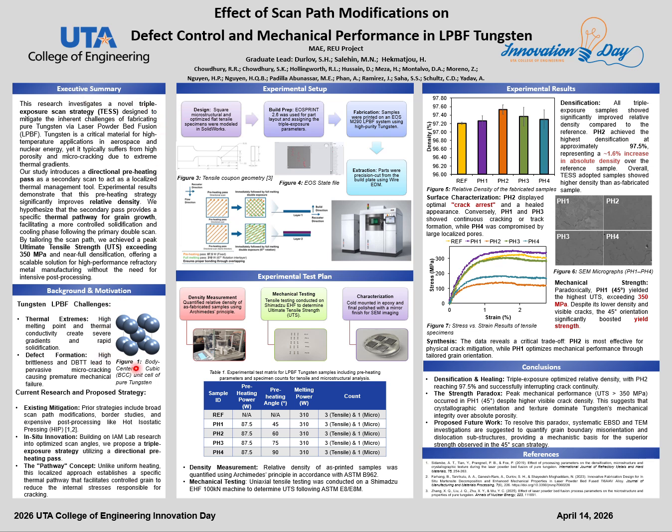My topic will be on tungsten, which is a critical refractory metal, very popular in aerospace and nuclear applications. But the issue with tungsten is with laser powder bed fusion. Why? Because tungsten has a very high ductile to brittle transition temperature, mentioned here. But laser powder bed fusion is an extremely rapid heating and cooling phenomenon. This yields pores, cracks, and defects in the tungsten sample, which makes it really difficult to make a successful part.